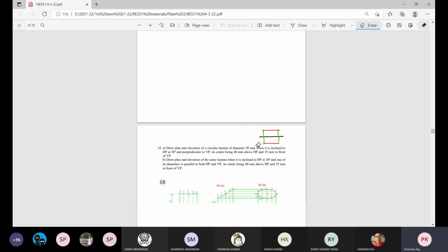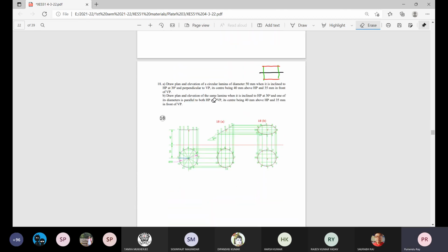The pentagonal lamina. Here we need 12 points to give along the boundary and draw the individual plan and elevation of these 12 points, and think of the circular plate as a whole, not as distinct 12 points, because these are connected by this logic also. The continuous connection of these points in sequence will give us a closed boundary, a circle. Its shadow, when you make it inclined to the HP on the other plane, will be that ellipse.